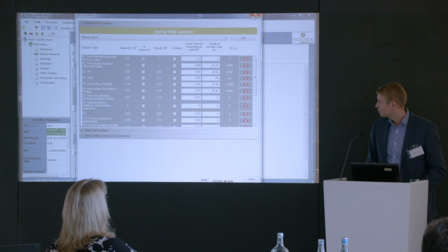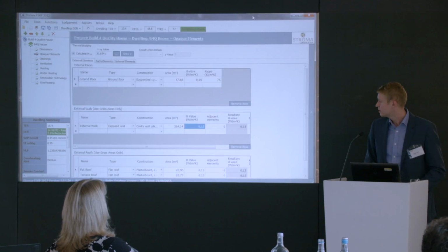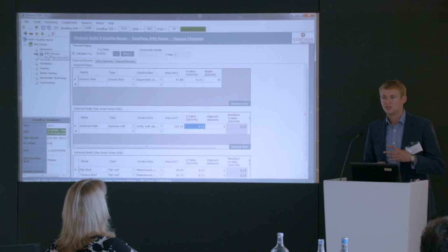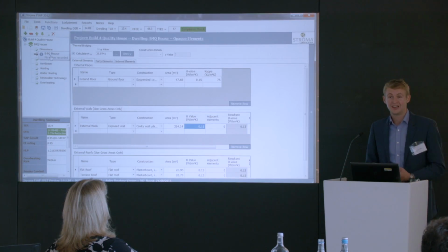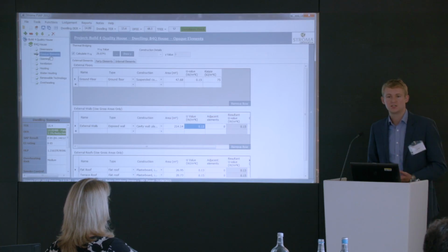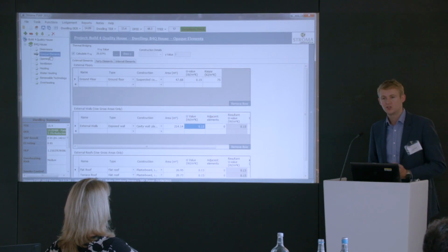if we did that, if we have a look, we go from 2.6% to 3.3. So actually, thermal bridging is a very big impact on the calculation. That's only one junction that we actually looked at. Granted, it was the junction that has traditionally the highest heat loss, but it is certainly worth addressing your other junctions where there is heat loss. And it's, again, improved the fabric energy efficiency.